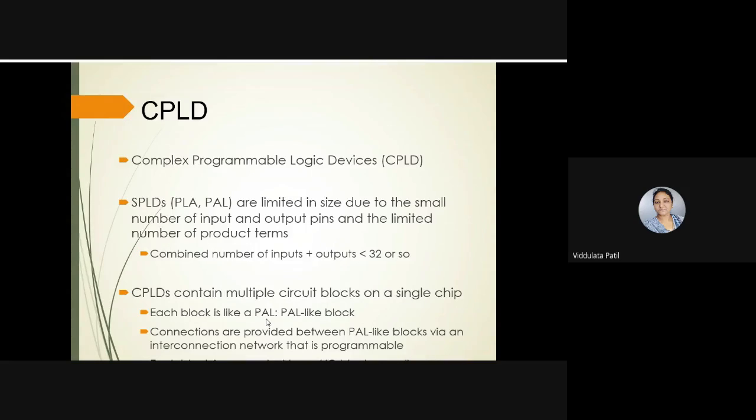That is why we are going for the CPLD. CPLDs contain more circuit blocks on a single chip, so it contains a number of PLDs on a single chip, and so we can increase the number of inputs for that particular IC, and then we can implement a larger circuitry on a single IC.